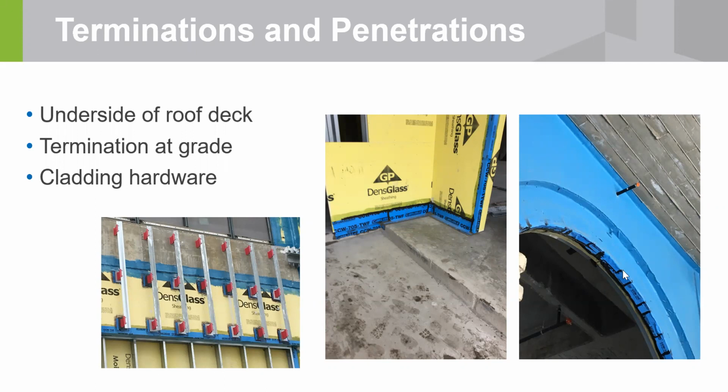And the photo on the right is showing a termination beneath the roof deck. So there's, we say, a 3-inch bearing onto dissimilar substrates. You'll do that with a peel and stick flashing or with an embedded reinforcement.